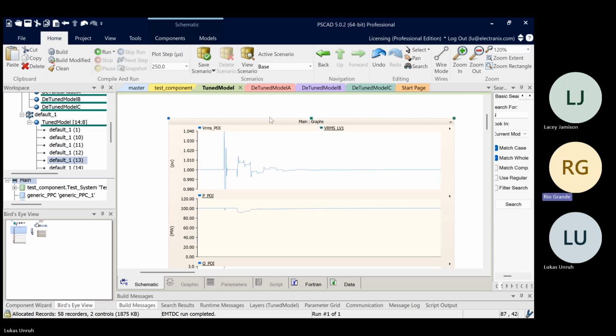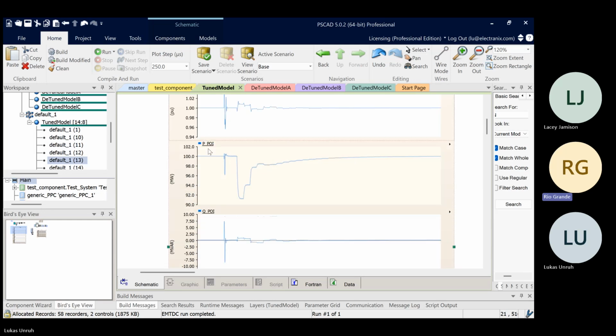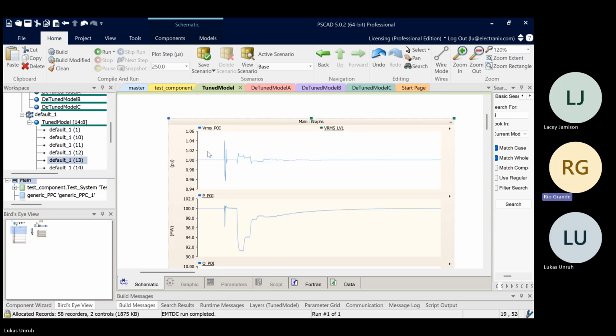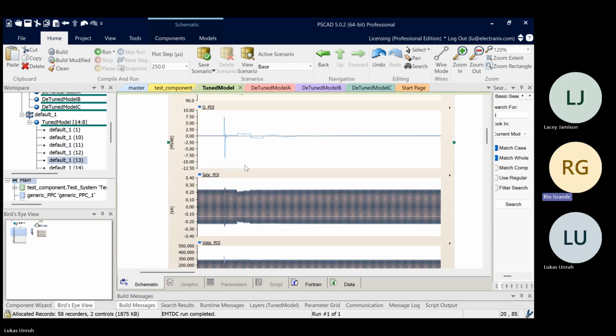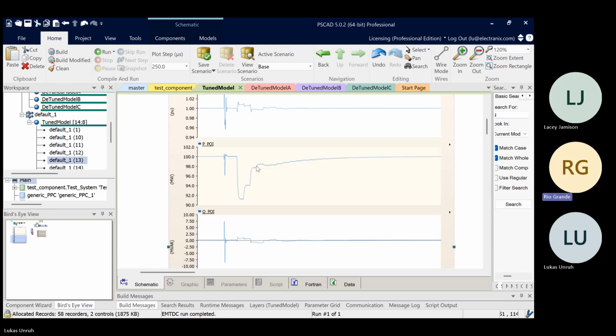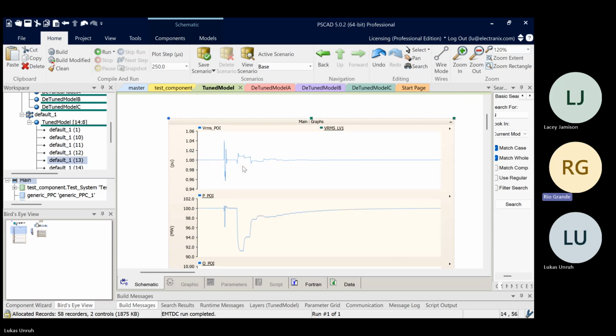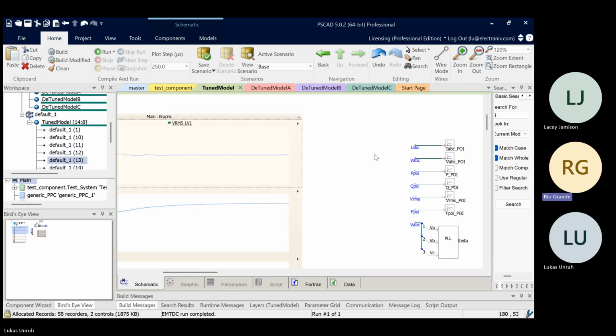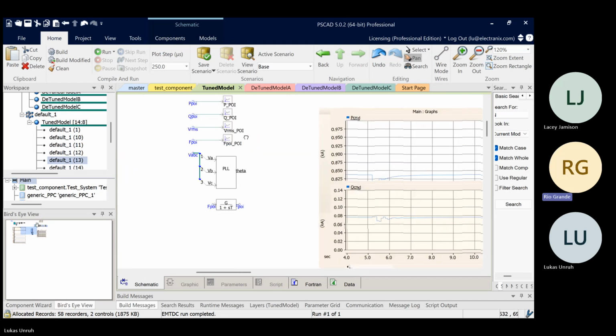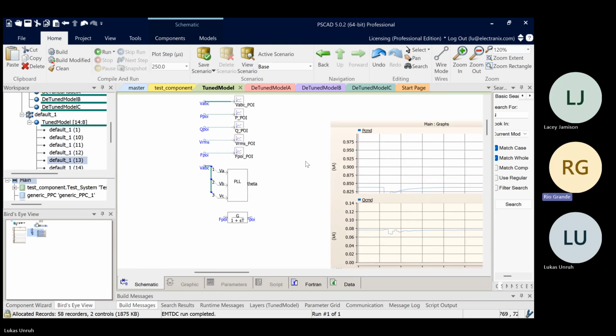13 was the phase jump. Something kind of interesting happens here with the active power. I'm not totally sure why it's doing this. I think it may actually be reading that phase jump as an over frequency, a brief over frequency. So what Alex was talking about actually does come into play in EMT as well to some degree.